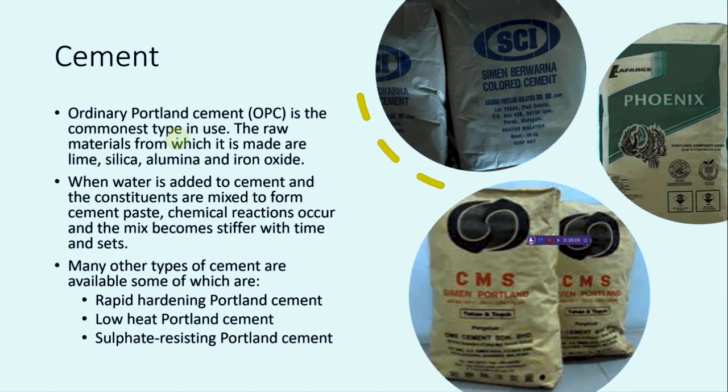It will affect it later, for example if the top hardens first compared to the bottom, in a thick concrete, okay, then there will be serious cracking because the bottom dries slowly, and the top hardens first. Okay, so we want to make it the same, so we use low heat Portland cement.